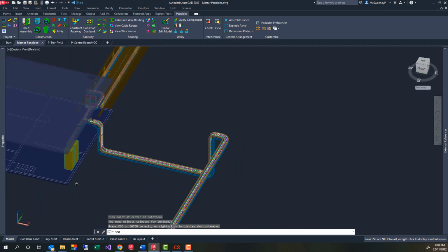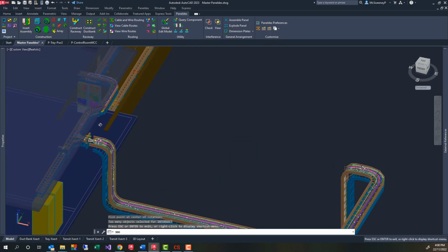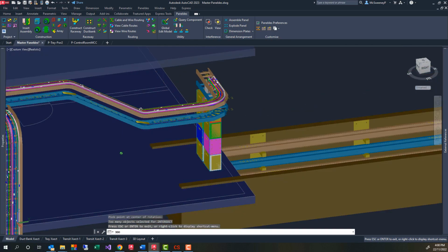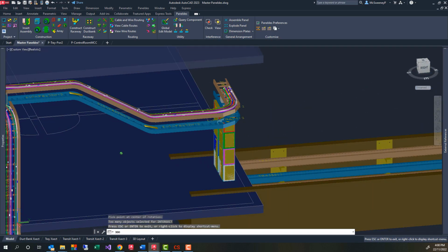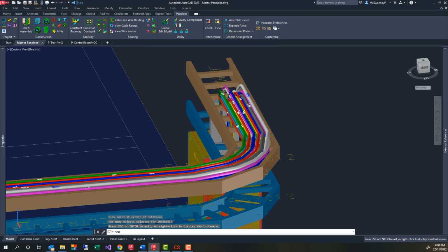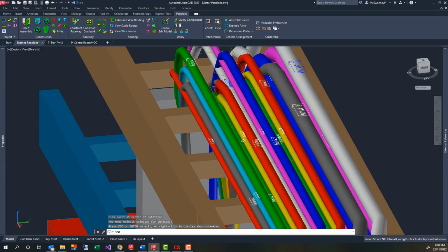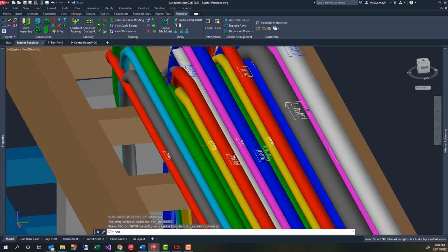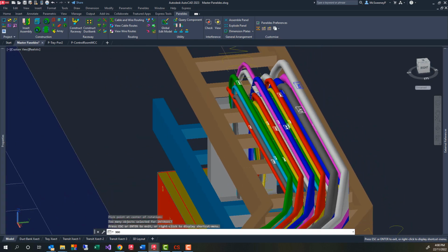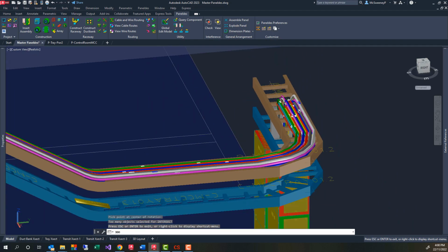When viewed, the cables are modelled far more accurately than when using traditional methods, such as using Excel-based calculations and centerline-based measures. This increased accuracy can save miles of cable and volumes of rework. The cables I have modelled are all of the cables running from the MCC out to the plant motors and heaters via the Power 1 low voltage tray.